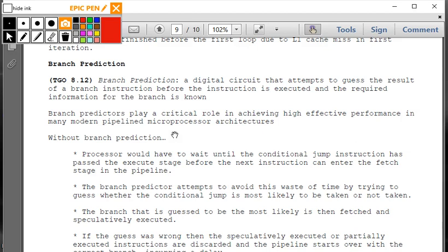2-bit branch prediction. We're going to use hysteresis, and what hysteresis is, it takes the previous branches and uses them as a way to determine whether or not we're going to take the next one. So if you've taken the branch, meaning that you've actually branched before, you're more than likely going to take the next branch as well. So if you branch not taking, you're going to not take it. If you go through the loop 100 times and you're not taking the branch, that means you keep looping through, and therefore that allows you to make that proper prediction.